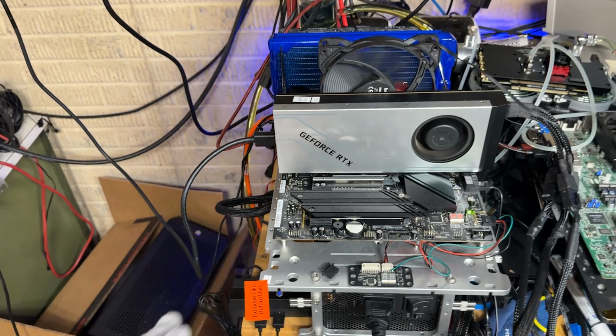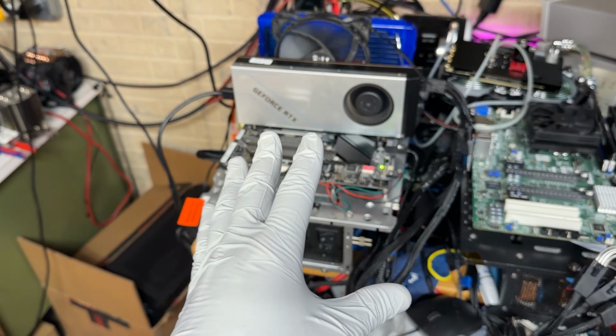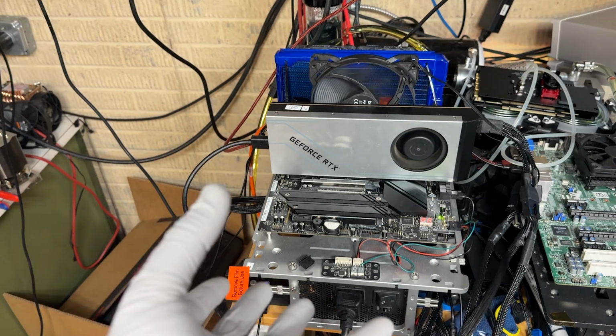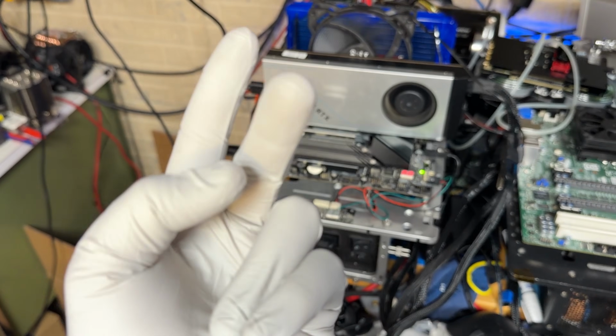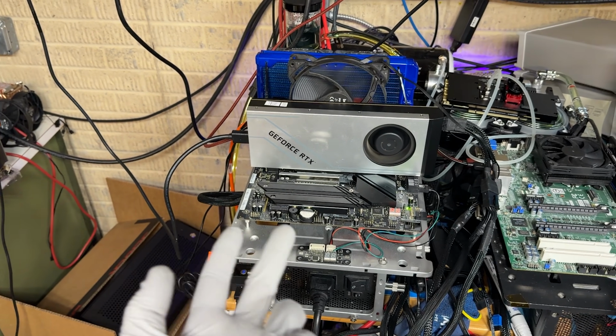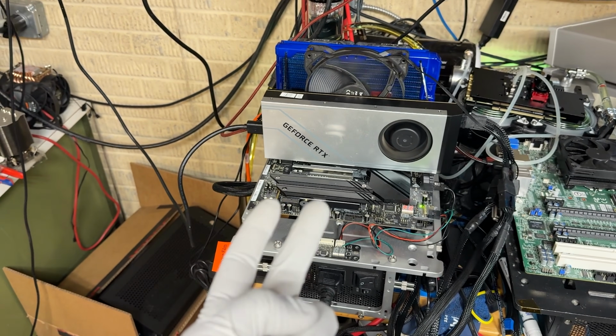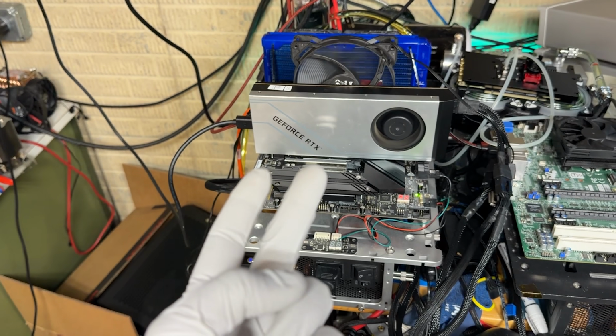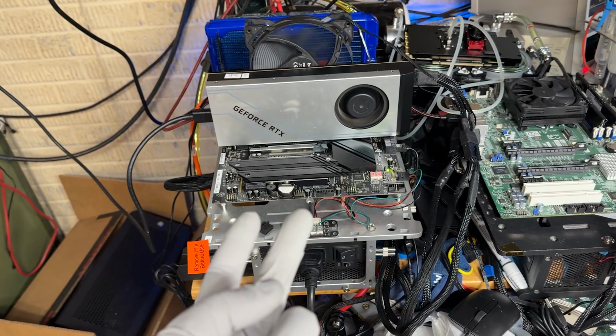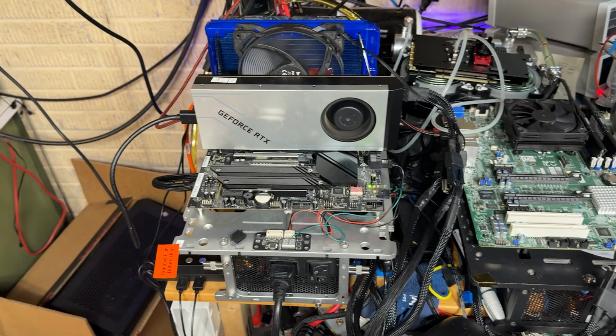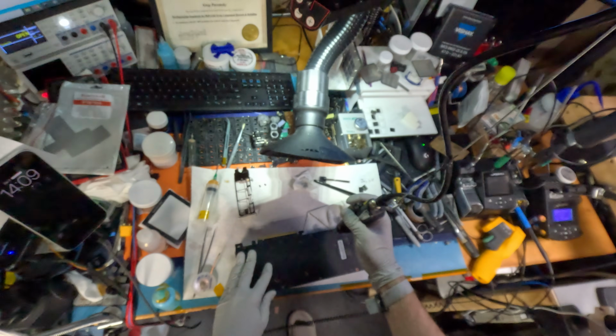And this is maybe potentially why I thought this would be an interesting video, to showcase a unique failure point. It's either the core is totally dead, or there's a cracked solder ball somewhere in a very unique spot that causes issues over 24 gigabytes. So that's what I'm going to do next. I'm going to basically reball the core. I'm going to take it off, and we're going to see if that's the issue.